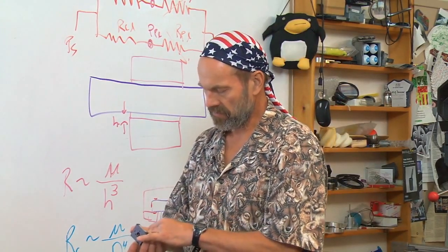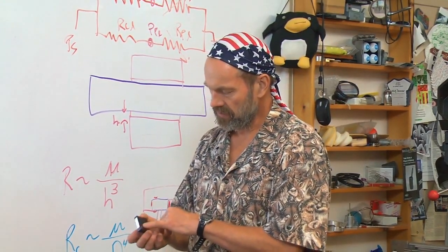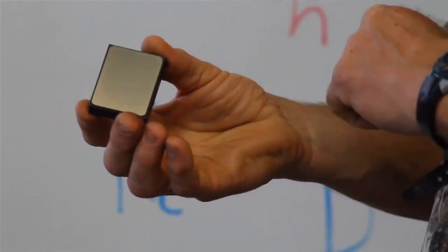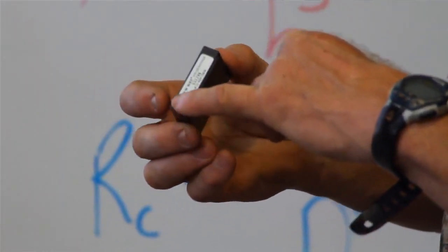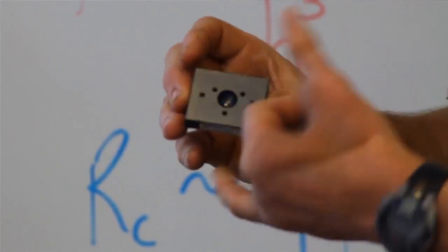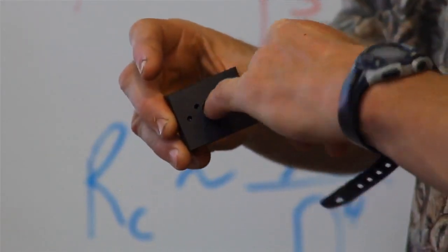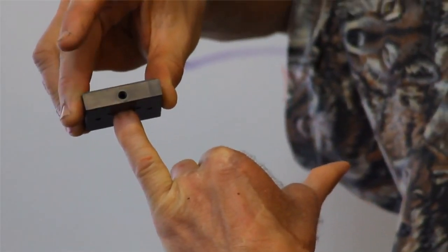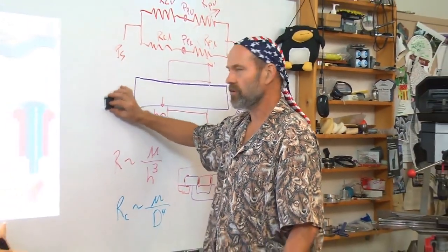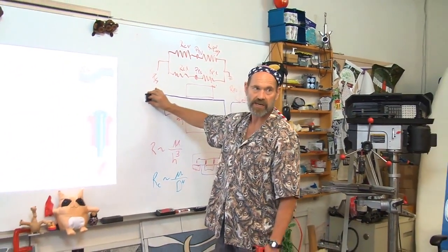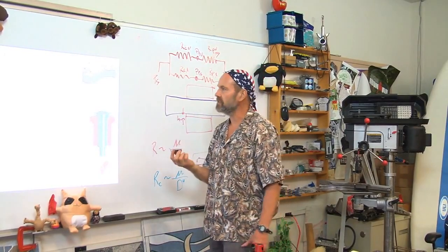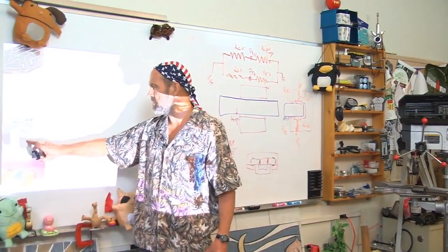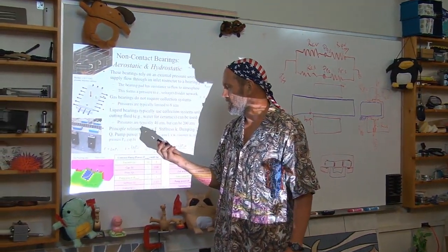And what New Way does, he takes porous graphite, bonds it into a metal housing, then, for example, a spherical element allows it to tilt self-aligned but very stiff rigidly in the axial direction. Put the air in, and then with air in, it'll float on a thin layer of air. Think air hockey table.